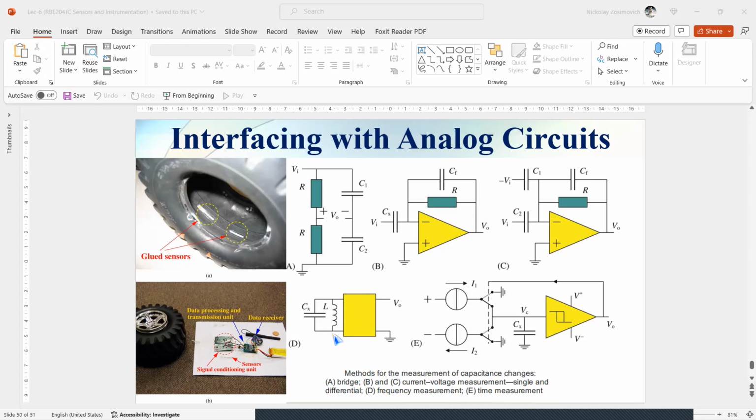Another approach to measure tire strain using a capacitive method has been to fabricate a particular strain gauge consisting of a pair of interdigitated flat electrodes on a flexible polyimide carrier. The gauge glued onto the inside of the tire responds to strain by a change in capacitance.